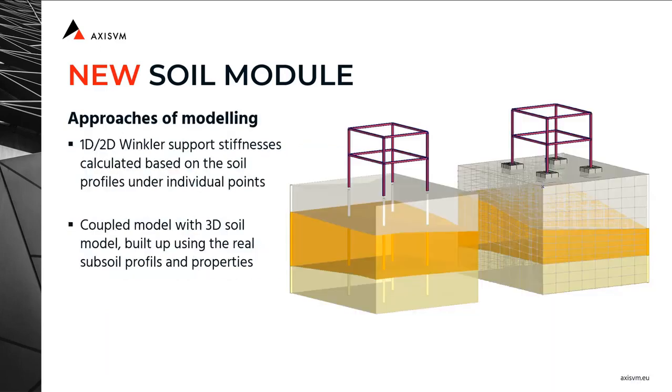Soil module offers two approaches. First one is a more straightforward approach building on top of already available functionalities, which is the 1D, 2D Winkler support stiffness calculation, but based on the soil profiles under the individual support elements. The second one is a more sophisticated approach where the structure and the soil form a coupled model. The soil is modeled with 3D soil elements using the real subsoil profiles and properties.